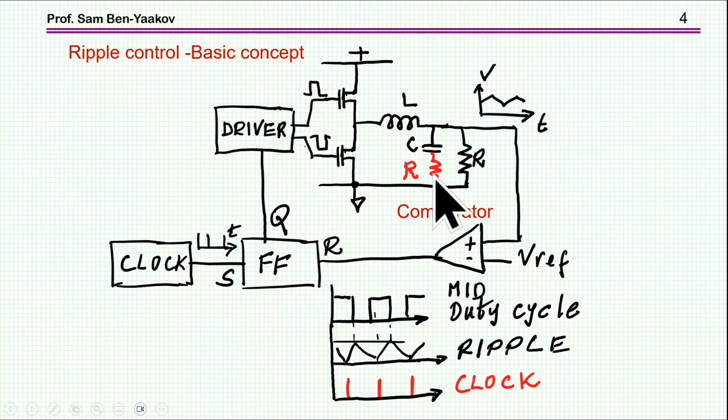Here is a zoomed part. We see here the excitation, plus minus 10 millivolt. And we see here the output. This is of course the ripple, the 300 kilohertz. And I'm also showing here, sort of pushing it to the high frequency at 87 kilohertz. Obviously, we don't have too many sampling points here, so this couldn't be a very nice waveform. It's a fairly large signal, 10 millivolt, and this is for 87 kilohertz. Still, it's working okay. Well, not very elegant, but it's okay.